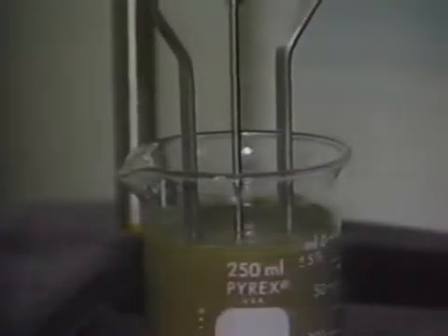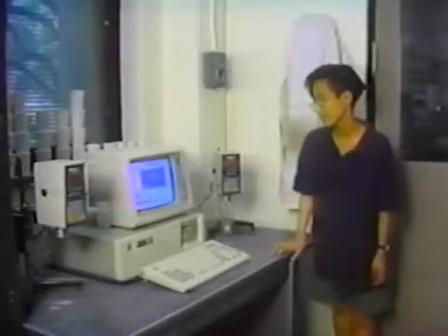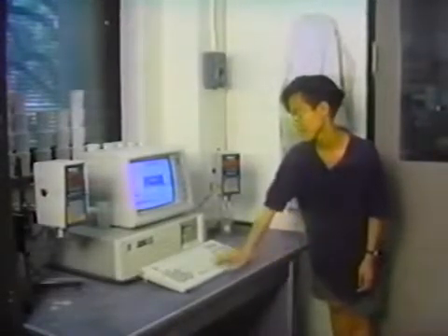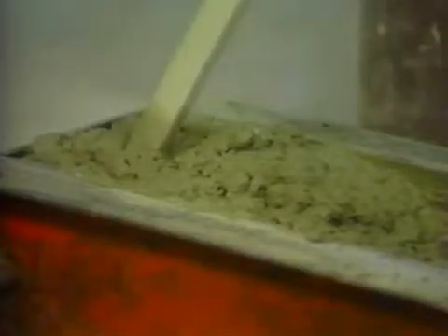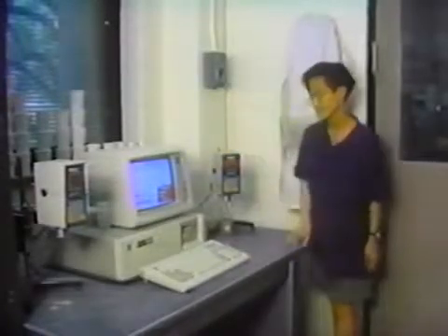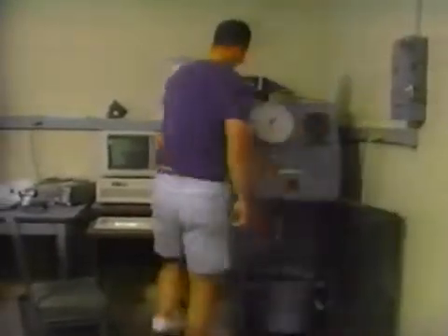Properties such as viscosity and the initial resistance to flow are used to characterize liquid materials. Water is a liquid with low viscosity and a low initial resistance to flow. But concrete, mortar, and fresh cement paste have much higher viscosity than water. Vibration is often used to overcome this resistance in concrete. In the lab, fluid properties of cement paste can be measured with this Brookfield rheometer. Researchers use larger equipment, such as this Tattersall rheometer, to measure the properties of mortar and concrete.